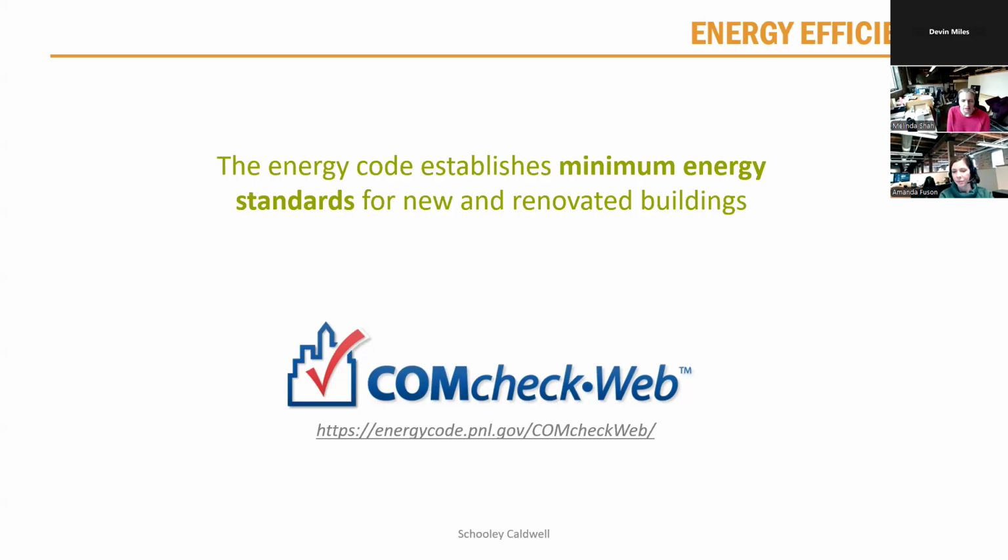There are a lot of leeways for older buildings, and really what you're going to have to do is sit down and start looking at what makes sense to do in your building, what doesn't, especially if you have masonry walls. We have to be careful about adding insulation to them because the last thing you want to do is add all this insulation and then cause dew point problems, which can cause mold to grow. That is not going to do anyone any favors.